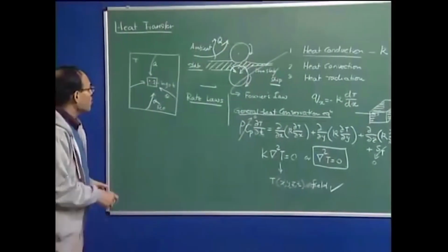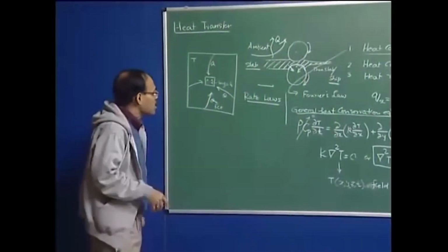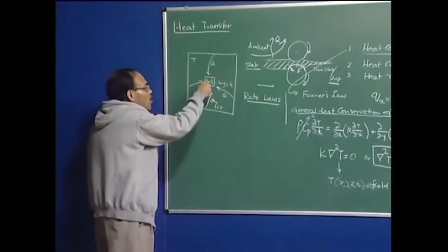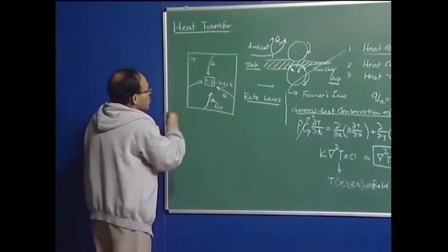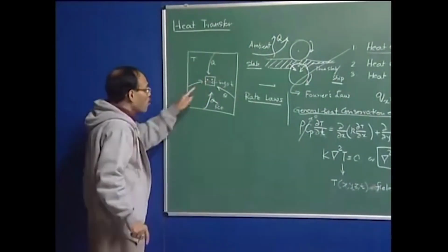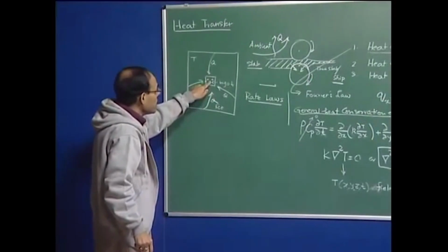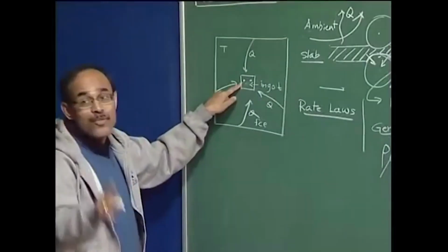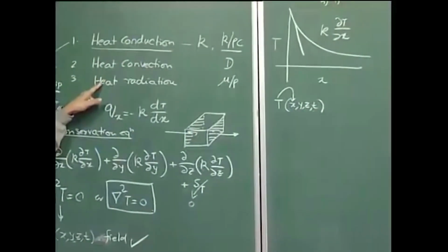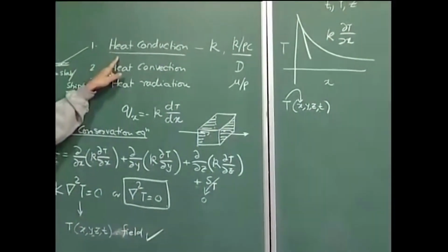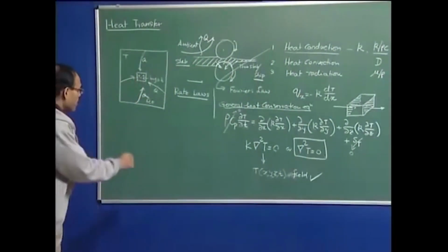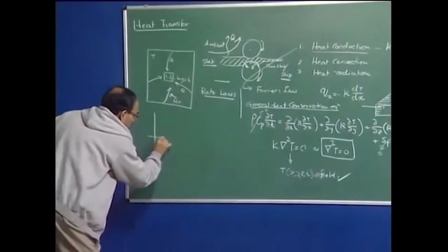I will know, for example, my knowledge of heat transfer tells me that the rate of heating at the center is going to be least, because the heat has to reach from the furnace to the surface, and then it has to go inside the solid, and this is the conduction process, which is a molecular process. And of the three mechanisms of heat flow which I have indicated here, heat transfer by conduction is the slowest process. So, therefore, I can say that this center point,